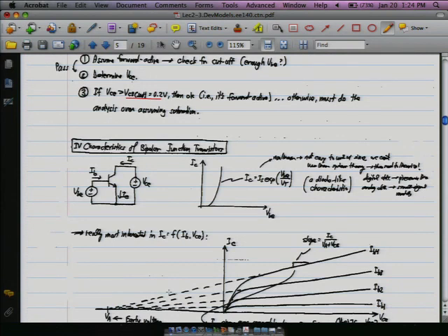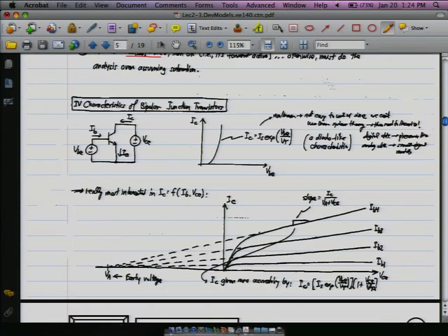So the first thing is that this is nonlinear. It means that as it stands, this IV curve, the collector current versus the base voltage, is not easy to use. It's not very useful as it is now because we like to work with everything being completely linear. This makes the math easier, and we're engineers and we're lazy. So we like the simplest models we can get.